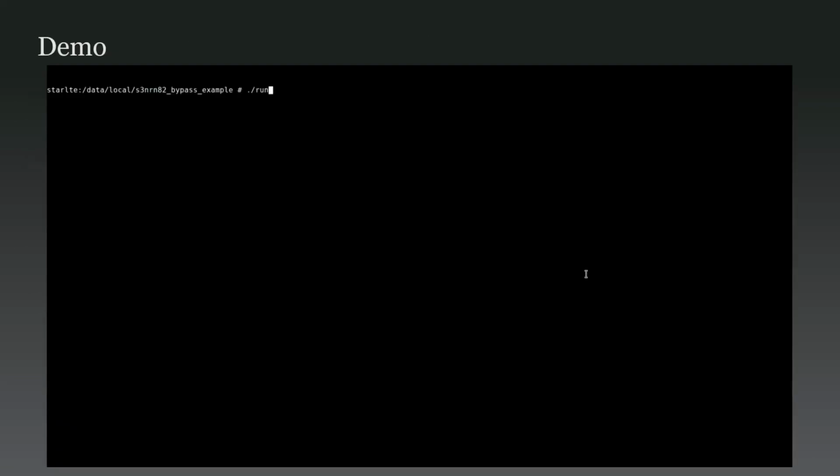Because I didn't know where the program counter needed to jump to in the bootloader anymore, by virtue of the fact that I couldn't see the bootloader, what I ended up doing was processing from address 1, or rather program counter address 0+1, which is how Thumb code addresses code in this manner, and let it run until it found an endpoint address which would allow it to jump into the raw firmware.